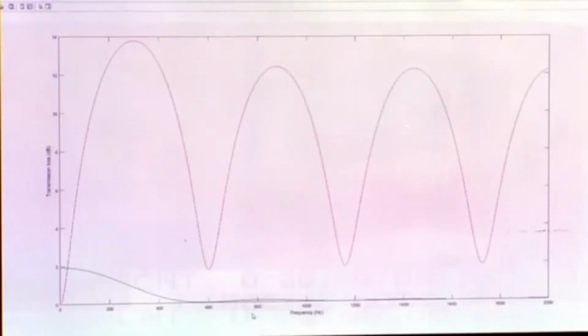So, you see the dramatic increase in the transmission loss, there is no comparison actually. So, compared to the sudden expansion, the conventional chamber produces a much better performance, but in fact at low frequency it does go to 0, but that is completely offset by high transmission loss once the performance picks up. Another thing to be noticed is that transmission loss never quite gets to 0 even at the resonance frequencies where I am pointing here and here and so on. So, this is quite different from the simple expansion chamber.